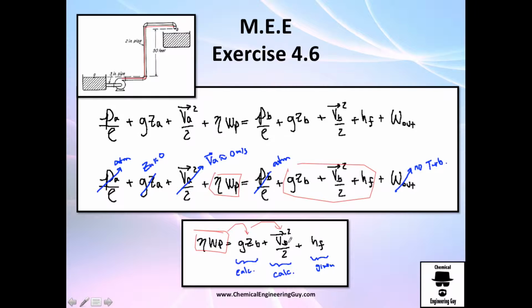Second thing, it needs to add velocity, so we need the pump to add velocity here. And not only that, guys, we need to recover all the friction loss in the pipe right here. So make an analysis, guys, on why we need the pump. We need the pump to overcome the height, to give it a little bit more velocity. I mean, you always need to give velocity if you're going to be throwing away the liquid. And of course, overcome all the friction through the pipe.